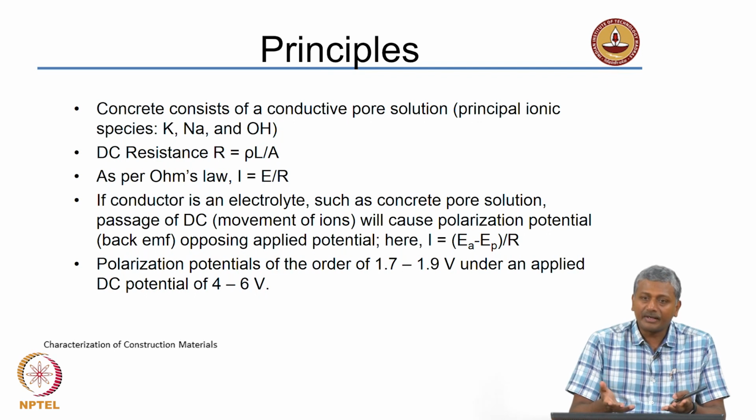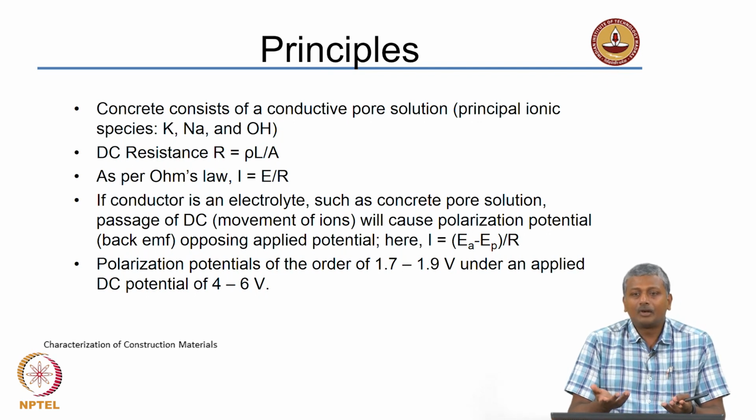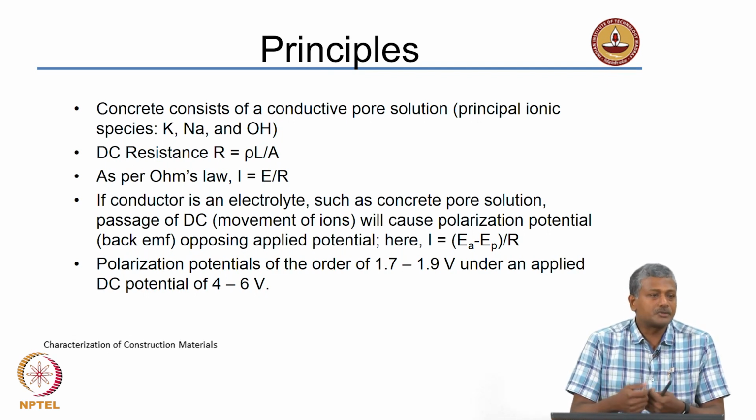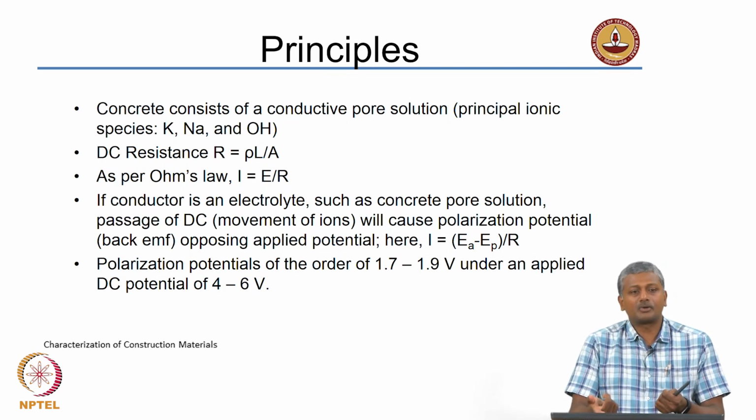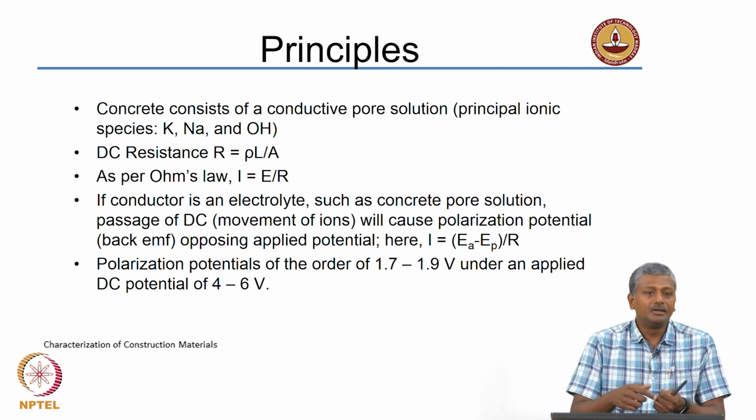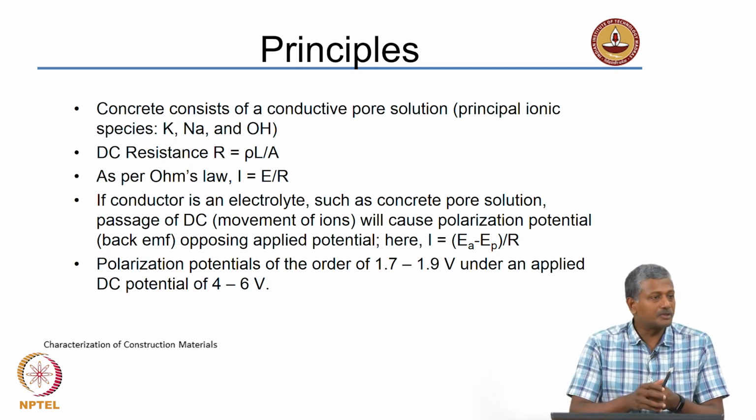Of course, if it is dry concrete, again it will not be able to transmit anything because water is not available to carry the charge. And the fact that you have ionic species dissolved in water allows the conductivity across a path within the concrete.